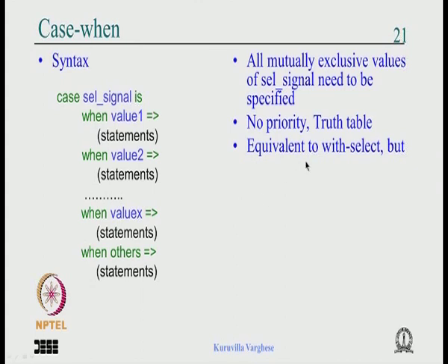It is equivalent to with select, but there is a difference. You can specify multiple outputs in each case. You can do nesting, that means a case can be nested within another. Suppose you say when value 1, you can have another case statement, or you can write an if within one of the choices. So you can have a very complex combinational circuit specified by this syntax.